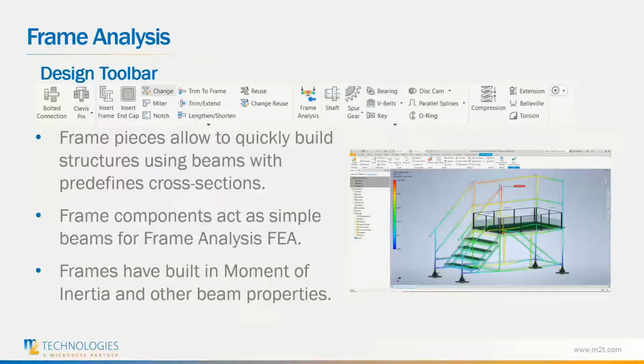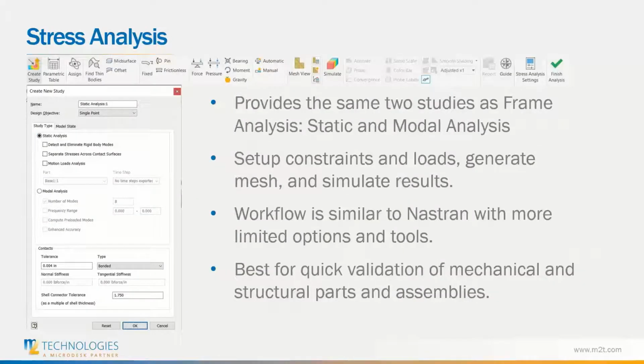However, if you have more complex 3D parts, you can use the stress analysis, which allows for the same static and modal analysis done in the frame analysis. However, instead of using simple beams, it will create a 3D mesh to define the part.